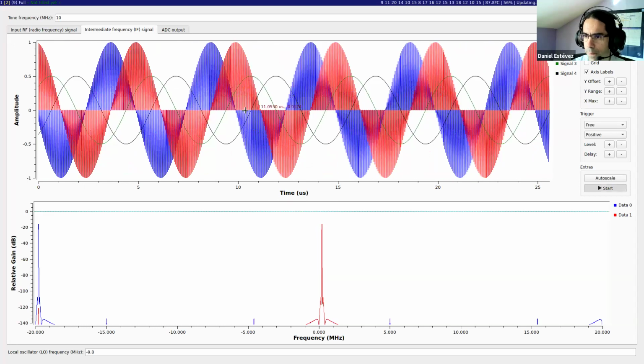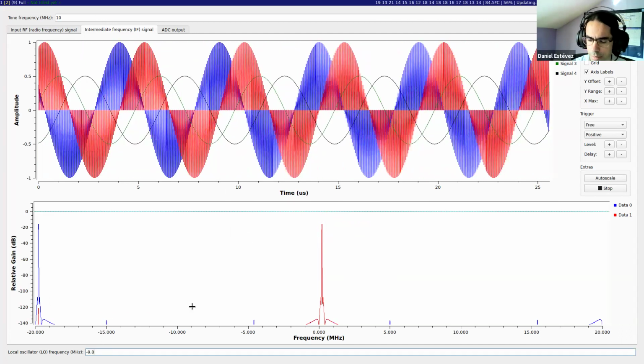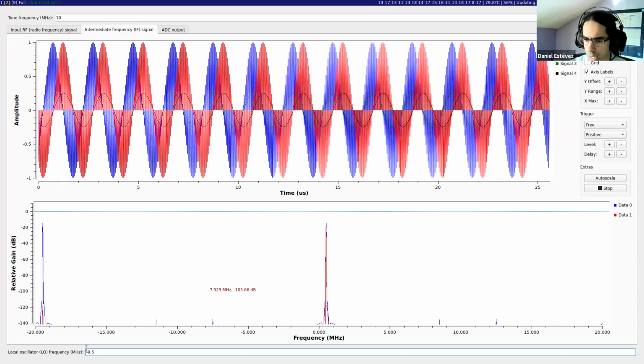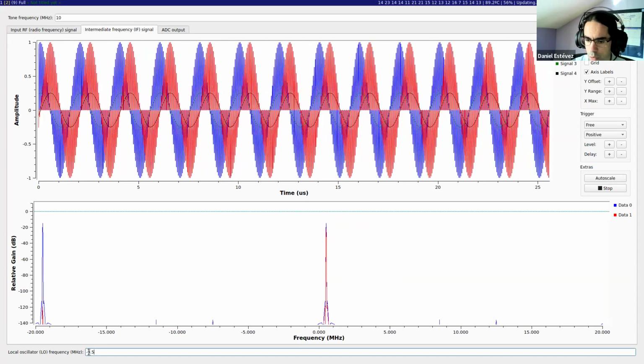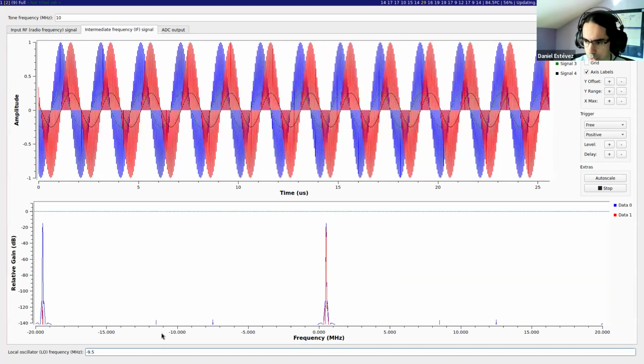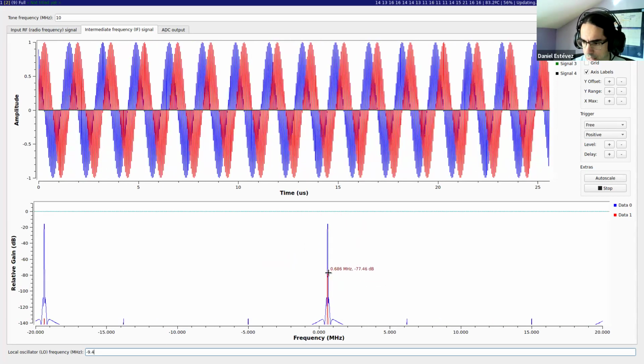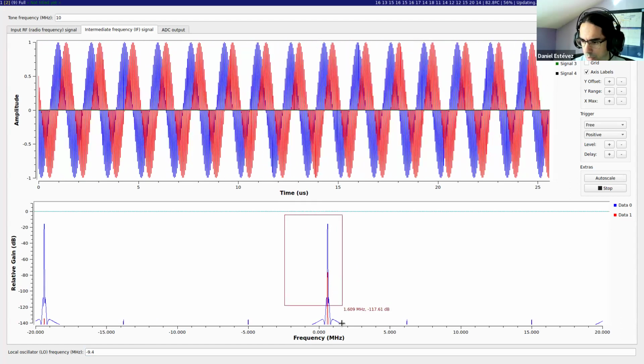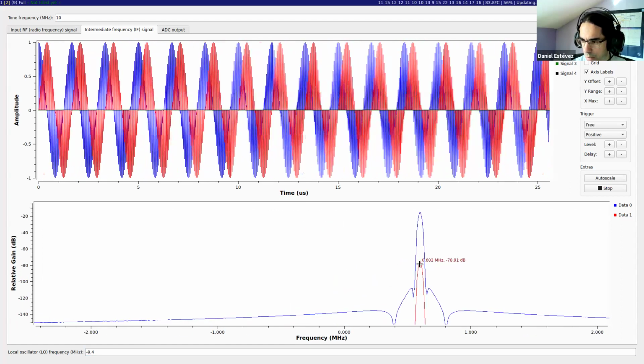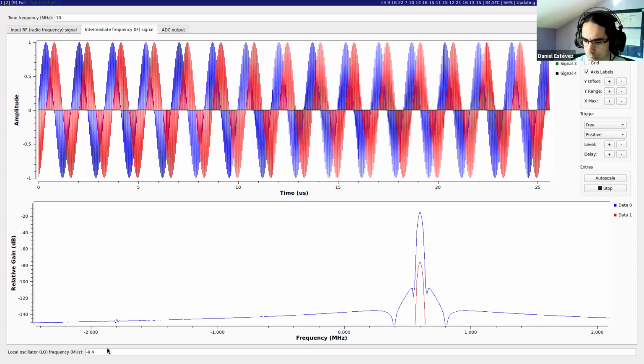So again, the filter removes the high frequency signal, and in the filtered version of the signal, we only see the thing which is at 200 kilohertz. The other one is highly attenuated. And what we can check is that now, as before, if I set the filter to -9.5, -9.4, the filtered signal starts to disappear because the cutoff frequency for the filter is at plus 500 kilohertz.